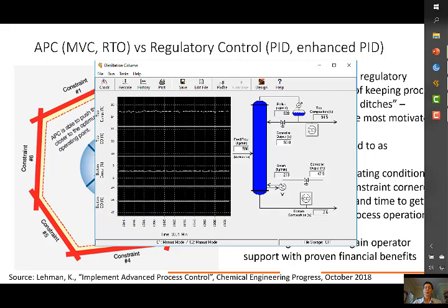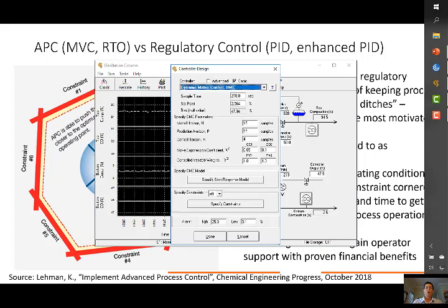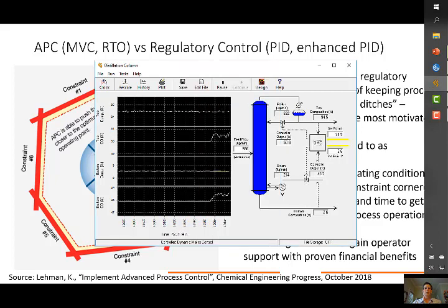I would actually cascade these to a temperature control, but that's just me. But you can put these in DMC mode. And in the coming slides, we'll talk about all of these specific DMC parameters, which are similar in effect to gain, integral time, differential time, etc. So we can do that and put it in, and we see it goes kind of wonky right off the bat, but that's okay. Anyway, just wanted to show you that the control station software does have the capability of simulating things with a DMC controller, which I'll talk to you about a little bit more later.